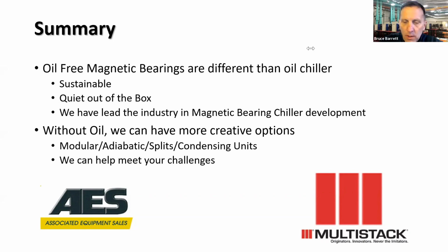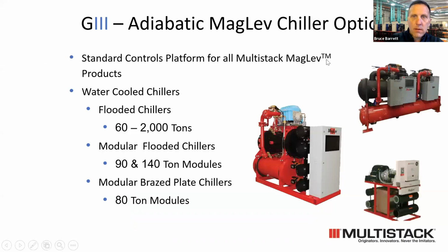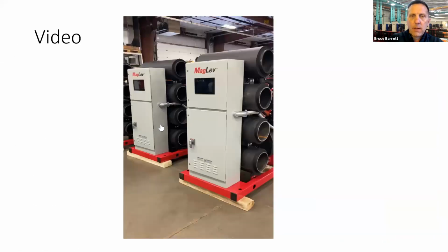Great question. So your typical turn down in a water-cooled machine, I'm going to go back to the presentation just to show pictures. All right, let's talk about the modular first. If you've got multiple modules in an array on a variable flow system, you can typically turn down to 40% of your module's flow.